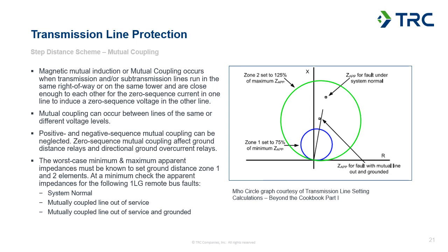Generally, this type of analysis we're going to do directly in Aspen. We're able to model the mutual coupling impacts within the transmission line models.